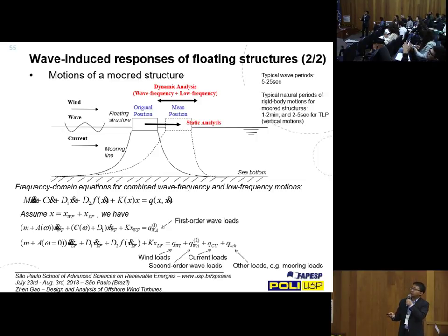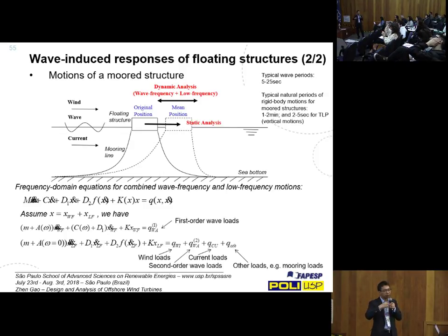The mooring system is basically designed to constrain the motion of the platform, but it is not like a fixed structure. So you allow the wave frequency motion under the first order wave loads. You cannot restrict that motion, because the first order wave loads are very large. If we want to restrict this motion, then all of the loads will be transmitted to the support structure.